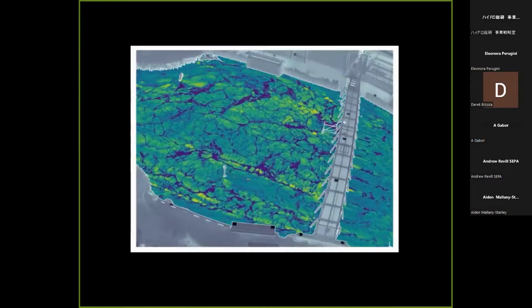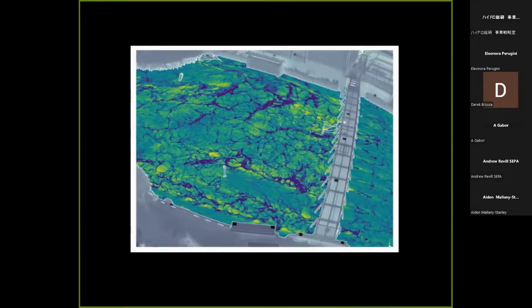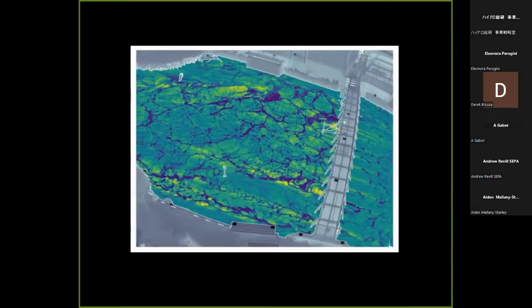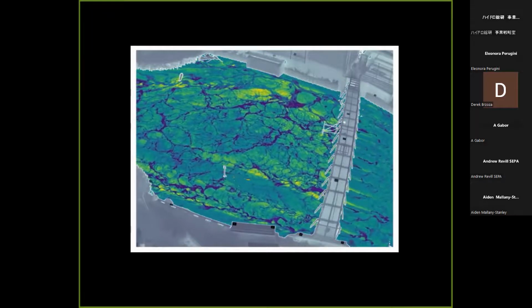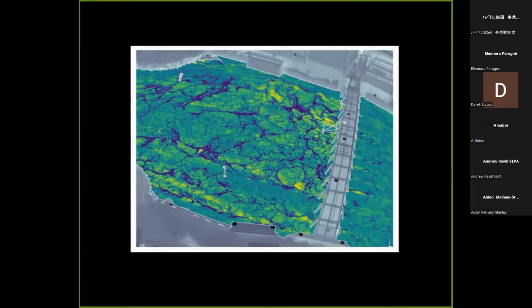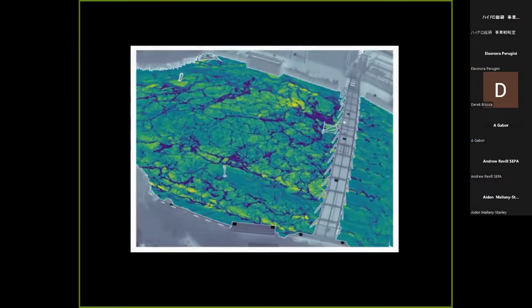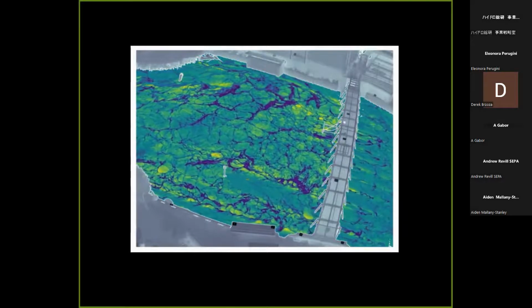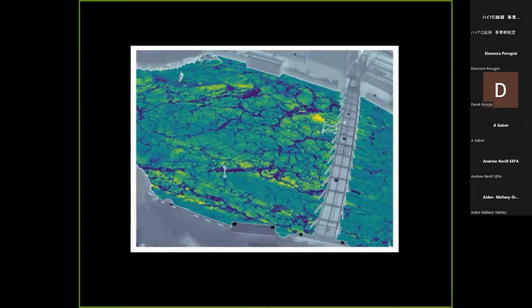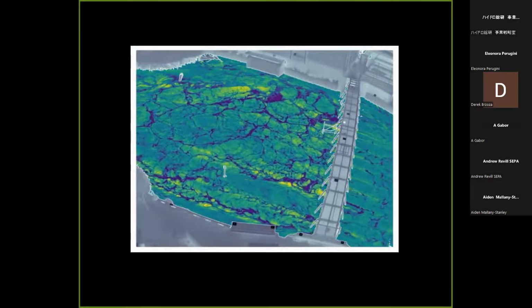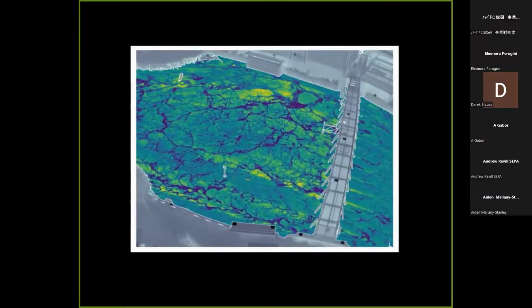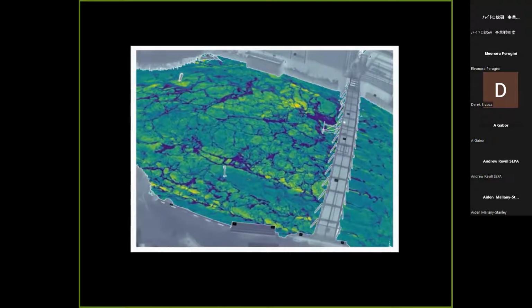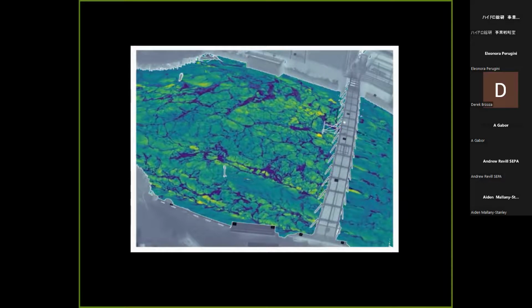And from a practical standpoint, just as far as velocity measurements, I just want to point out how we have this rich texture everywhere in the image from riverbank to riverbank. This means that we can make continuous measurements really at any location without any need to add seeding or to add any kind of illumination, because the signal that we're tracking is emitted by the water itself. It's not a reflection from an external light source. So this allows us to make continuous measurements over the entire field of view, and it allows us to do it at very high resolution without needing averaging, which means that we can capture instantaneous velocities and calculate metrics of turbulence.